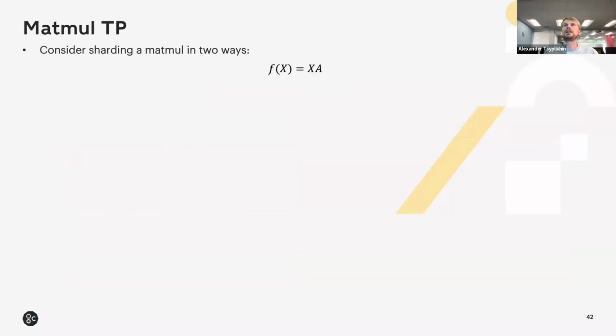In this regard, it helps reduce the memory pressure, because the operations, when distributed across more than one chip, require less memory to store, say, the weights of the model. And in some cases, these help to reduce the memory bandwidth pressure when loading the weights or activations from the external memory.